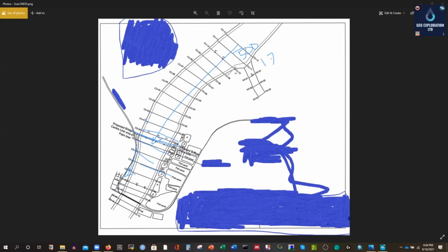And for the cross section you are inserting, whether you insert it right or wrong, it doesn't matter, but the model will assume that you are inserting from left bank to right bank. The maximum value will be most upstream, and the minimum value will be most downstream, and the cross section we are inserting will be from the left bank to the right bank. So that's why now we have an idea about which one is the left bank and which one is the right bank, which one is upstream, and which one is downstream.